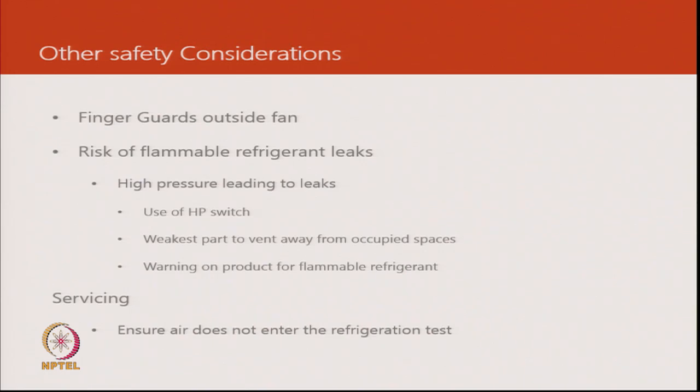Then I mentioned already the weakest part being vented away from occupied spaces, warnings on the product, and during servicing making sure that air in no way finds its way into the system, and if it does, then it is to be purged using nitrogen before any attempt to weld it or use any electrical input.